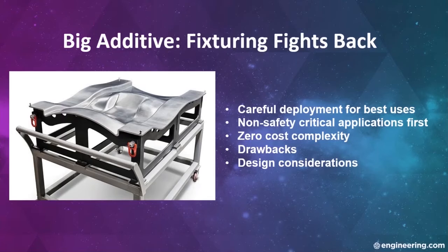Now, for the gas turbine, energy and process industries, this emerging technology is going to be very interesting because it can reduce or eliminate possible corrosion and stress concentration issues across a large assembly. More importantly, it can allow very tight control over thermal expansion. We haven't yet seen commercial equipment that can deliver a variable CTE material across a build, but multi-material additive already exists, and we expect to see this in commercial use within about 5 years.